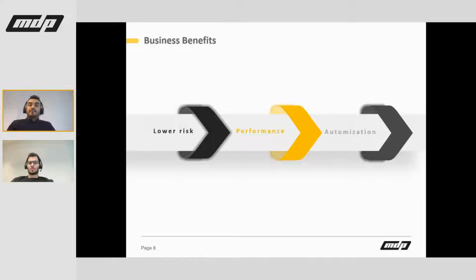It also improves performance because you need shorter transport distances to touchdown points, and you have faster processing of requests as the system carries them out automatically again. And because of automation at almost each movement, you will end up with fewer manual interventions, and thus they will be only necessary for correcting errors or placing or removing some pallets.